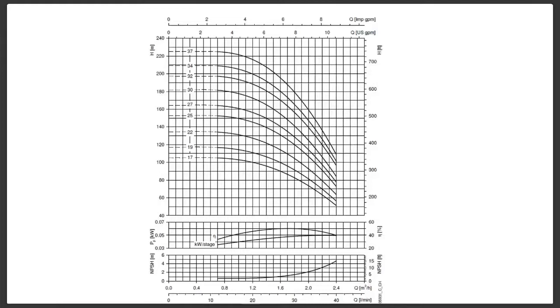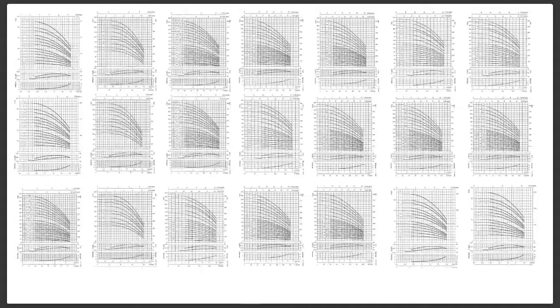You've got whether to do a 50 hertz motor pump, which will run at 2,900 RPM, or a 60 hertz motor based pump, which is going to run more like 3,600 RPM, or you can go higher than that. And at that point, you've got quite a lot of options to look at. So suddenly one set of pumps becomes a heck of a lot of pumps, basically.